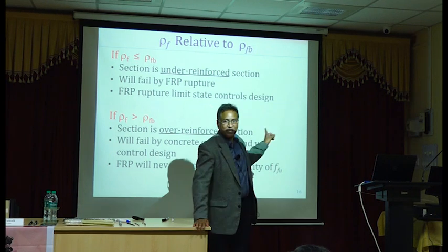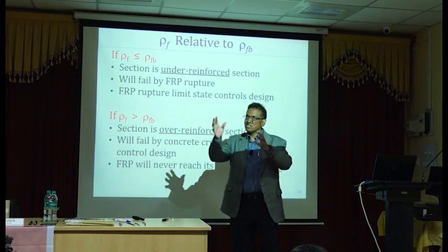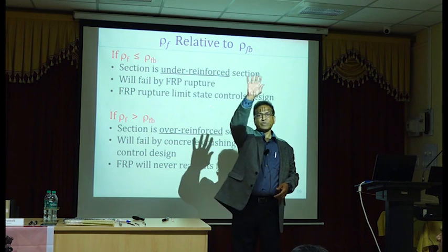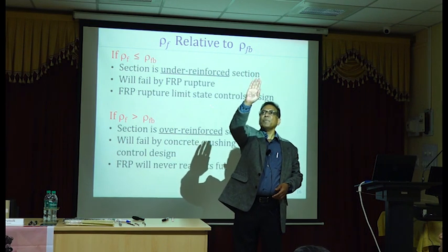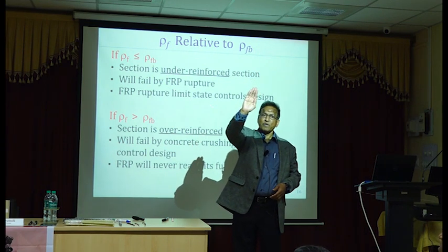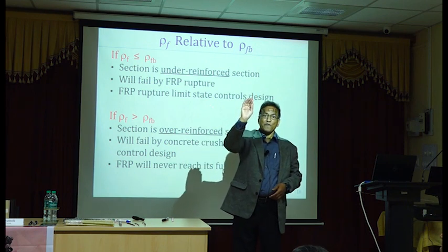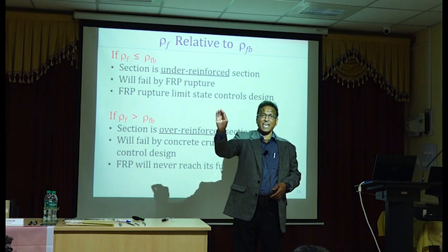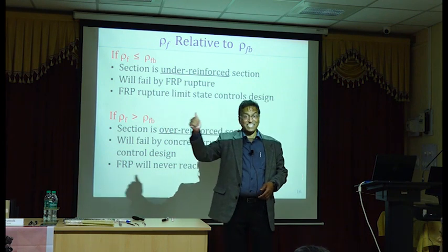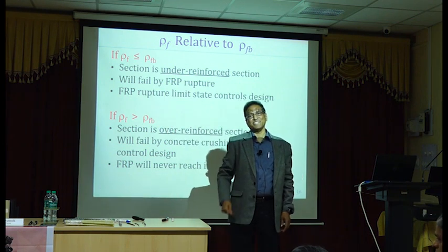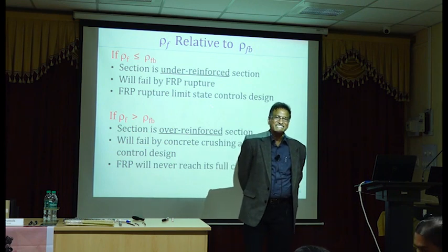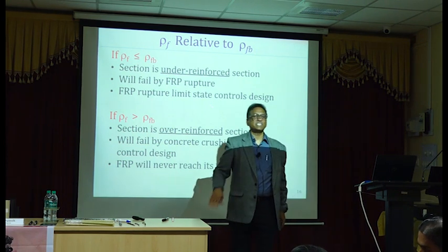Yes, that's what I am saying. That's exactly what we have said. So you have rho balance, you found out some value, right? And my actual rho F, which is FRP reinforcement ratio for the actual design, is greater than that. That's what we want it to be. It's just opposite to steel reinforced concrete.